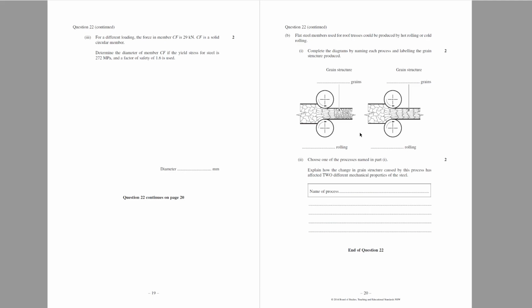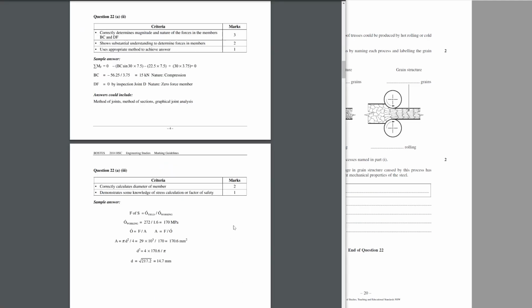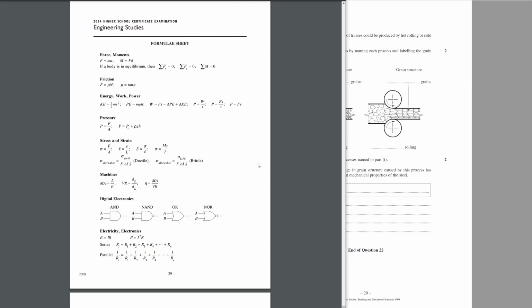Okay, so the next thing we have is a question. I had more than one student in the last month or so say to me, I didn't know what to do with this question. And I said, see how there was a force? See how there was a stress? See how they asked us to calculate an area or a diameter, right? Stress equals force over area, right? So where is that on the question sheet? That is here. Stress equals force over area.